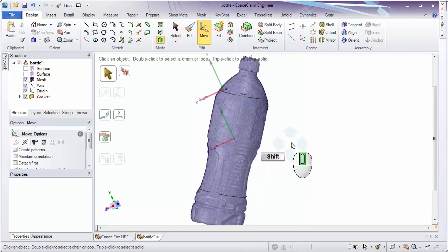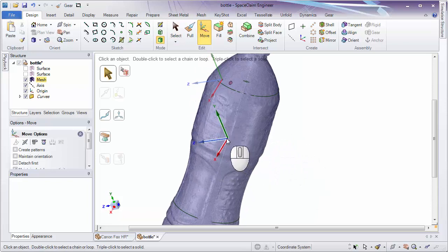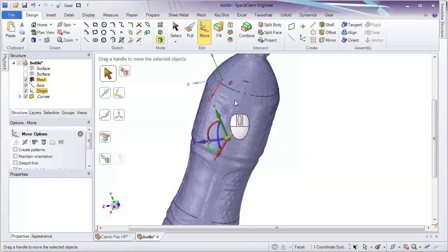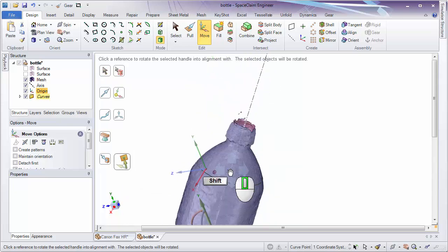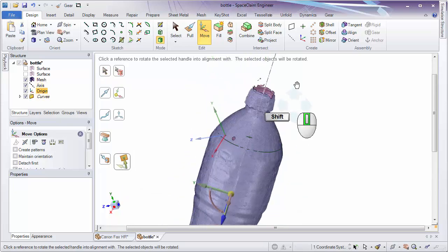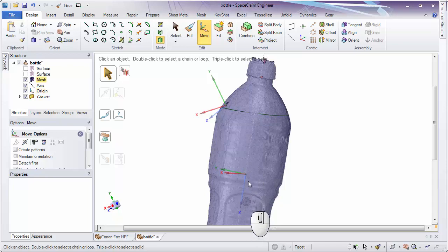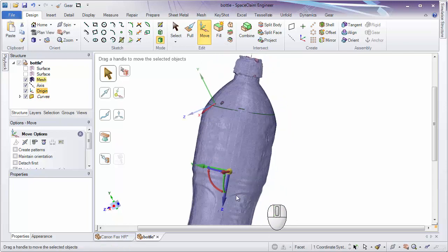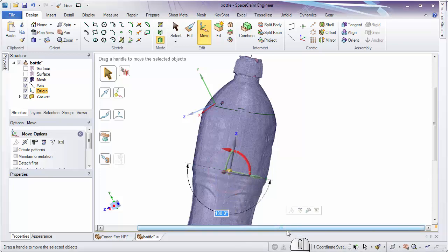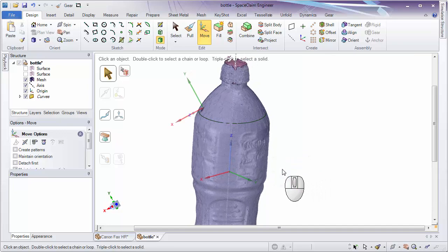So what we need to do is take the Move tool, select this local origin, choose the direction we want to be oriented to the axis. That's probably Z. And then use the Orient to Mesh, Orient to Object button and choose this axis. And you'll see the Move tool now has Z pointing in that direction. And if we want Z to be up, we could always use the Move tool, click on the local origin, type in 180, and now Z is up.